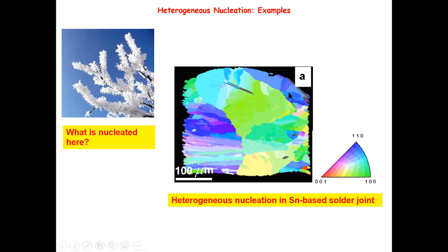But in the middle, you see this large one. It is probably because this one is not touching any copper surface, it's touching the air, so it has a much slower cooling rate, and it can afford to have a small nucleus grow and then expand to a large size. On this side is probably where you added the other copper later. So at this stage, I think the temperature is already reasonable. So you just have a very small amount of nuclei, but still they're heterogeneous nuclei. You see a lot of nuclei, but they don't have a chance to really grow very fast.